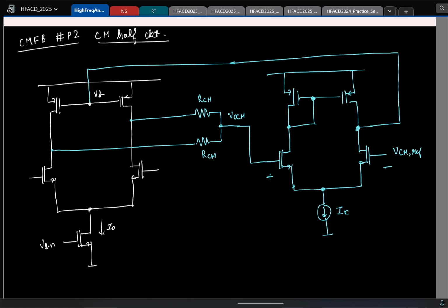So again, for common mode signals where I apply the same DC potential VCM here, both sides are equal, so you can short things. I'll directly draw it. Things will get put in parallel. So I have only one NMOS, 2x of the NMOS will be there. Similarly, I have the PMOS folded, so I have 2x of the PMOS.